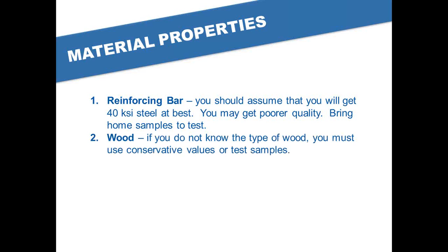For wood, either use very conservative values or bring back some samples to test. And also, if you use a lot of wood, you're going to want somebody during the implementation who knows how to grade wood, because you're not going to get the grading that you would here in the United States. You get, say, a beam with a huge knot hole in it that makes it essentially unusable, along with some really good materials, whereas here in the United States, that would have been graded out.